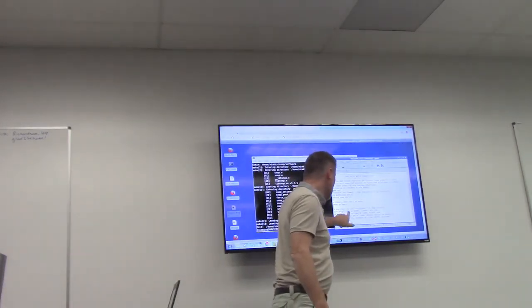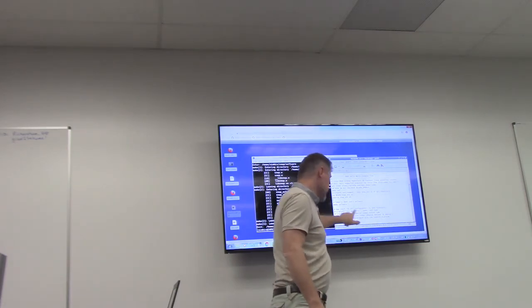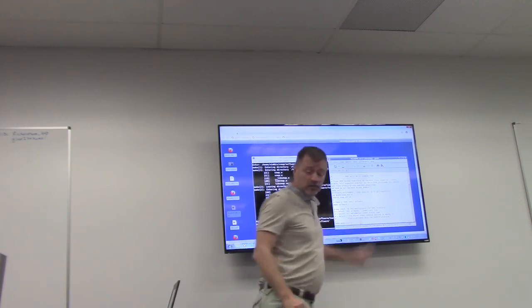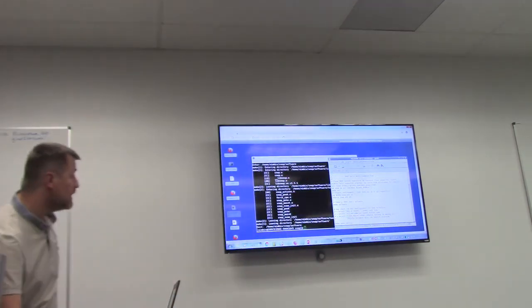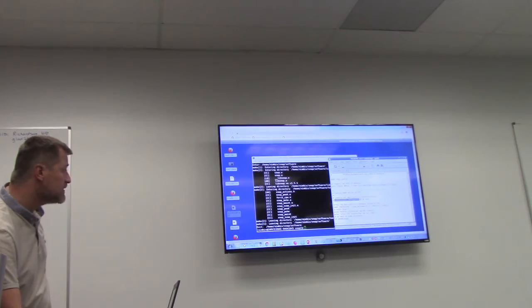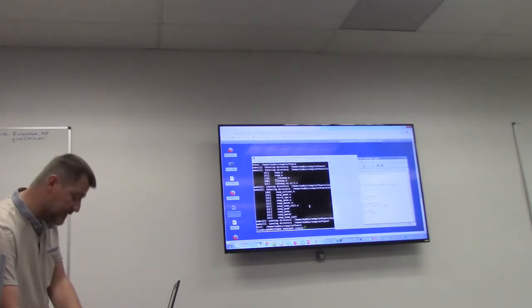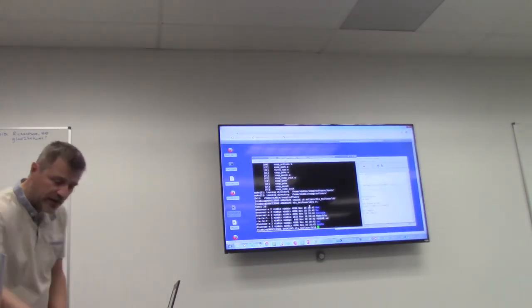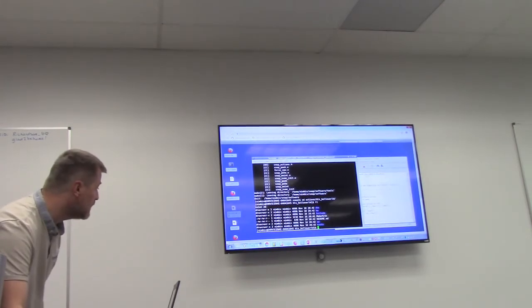We go to the configurator, we select the KU3, we have selected the second card, KU3. We select the HLS hello world, we select cloud build, that's what we have done. Okay? So now we go a little bit further. We have made the snap config step, so now we will make a first compilation. I will go into the directory: cd hello world, ll. I can also check the directory from here.